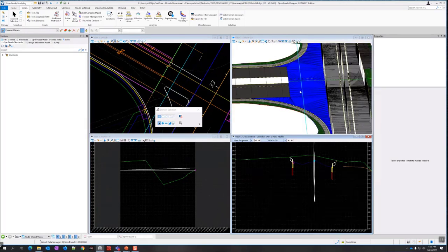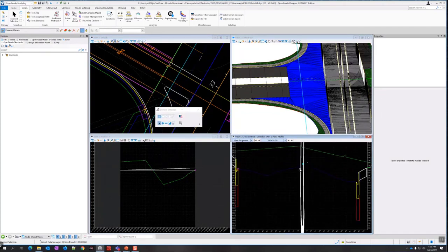So it's just going to massage that surface, get it like you want it. And it may help with cleaning up some of the jagged issues. At the end of the day, there's going to be a little bit, just because there's a bunch of small triangles in here. I wouldn't worry too much about it. You can tighten up the linear stroking as much as you want, but the tighter you go, it's more triangles and more complexity.